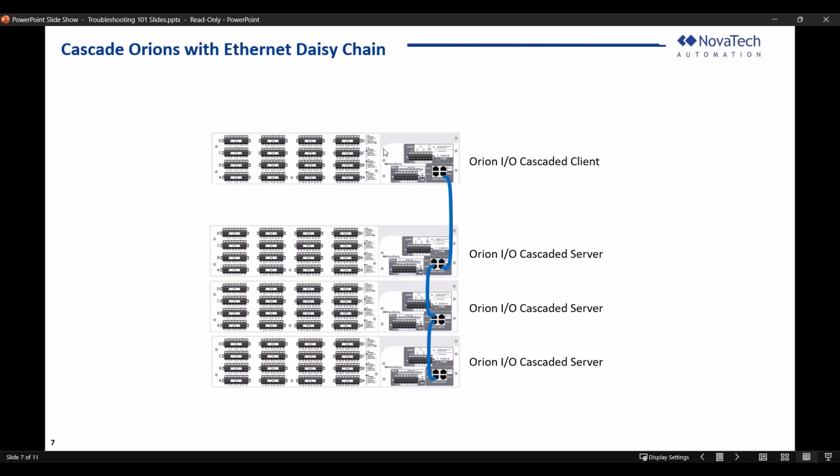It can act as an RTU, but we can't have a lot of points on it because of its horsepower. If you need more than 600 points, get an LX Plus, MX, SX, and so on. But if you have a lot of hardwired IO, one of those IOs can be your quote unquote cascaded client. It'll be the main one that you push the config down to, and it's smart enough to push the corresponding config down to the other ones.